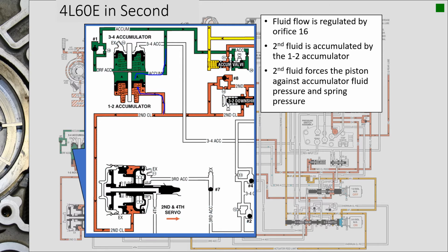Well, you know, if you're a brakes guy, you'd be like, well, you can't compress fluid. There's no way. There's a hydraulics law that says fluids cannot be compressed. Well, that's true, but when I have a higher pressure on this side, let's say 150, and a lower pressure on the other side, let's say 70, that 150 psi is going across the same surface area and is going to try to raise the 70 psi side. It's going to try to raise it to 150.